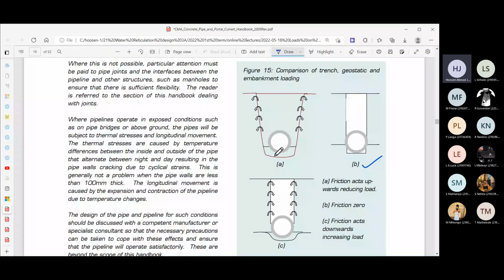So we want a bedding material that would exert a uniform pressure on the pipe and without damaging the pipe. So we've put a special bedding. We've selected what we call selected soil at the bottom underneath the pipe, and that would be the bedding of the pipe. We then come in back for the pipe over here.